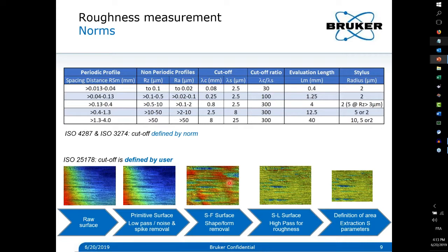So you may extract a bit of waviness, or you may extract the roughness or the micro-roughness. You just need to specify the cutoff. And in that case, as you will see, what becomes critical is to define the cutoff as per the application, and to know exactly which component of the surface is responsible for the main functionalities. And in that case, everything we do will be encompassed within the ISO norm.